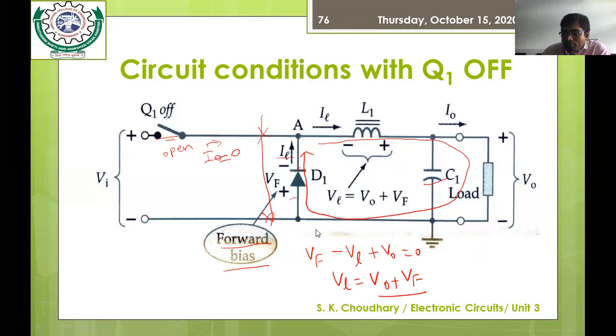See, if the diode is not present, then the voltage across the inductor becomes large enough, meaning it would keep increasing and increasing until it becomes large enough to break the transistor or switching device. It would damage the circuitry because there is no component in that circuitry except the diode that would catch and handle this inductor current.